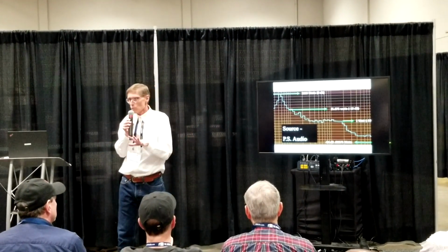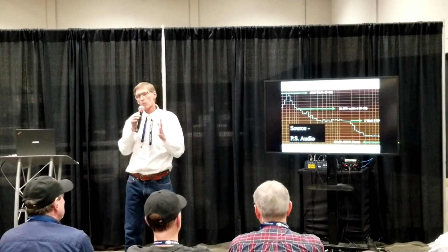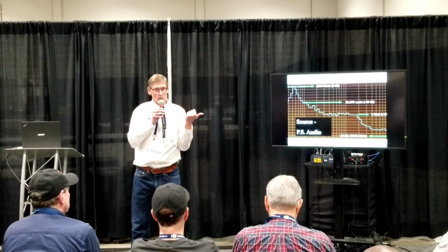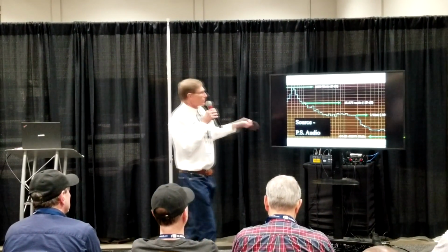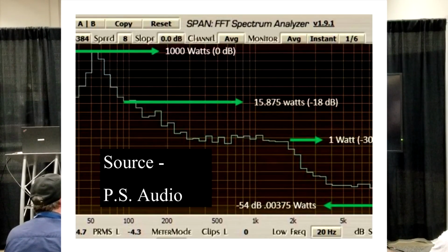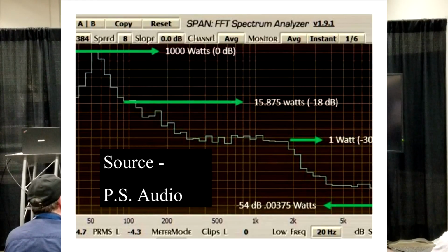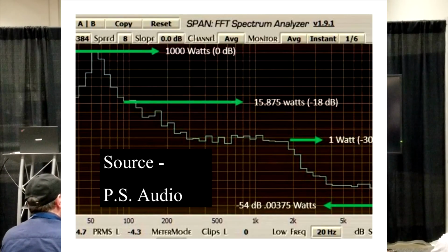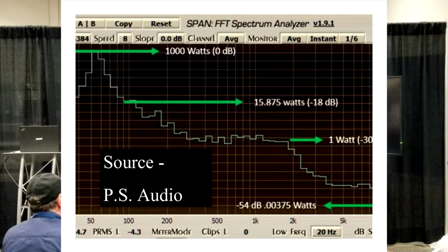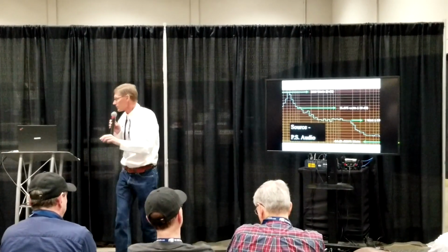So it's any wonder when you change from one cable to another, and hear differences in the bass response and things. This is why, that's where the impedance match is worst, and that's where we're working with the most amount of energy. That's where our reflections off the load are the worst. As we go up in frequency, we already learned that our cable looks more resistive. We don't have a lot of power to lose at the high frequencies either, but that's fine because it's into a more resistive load, so we have less reflections or incompatibilities as we go up in frequency. So that's in our advantage.